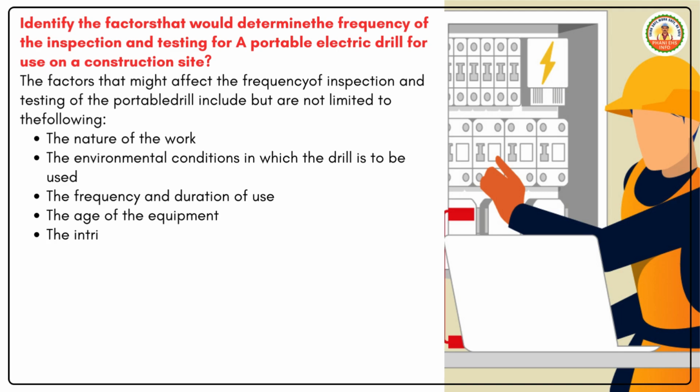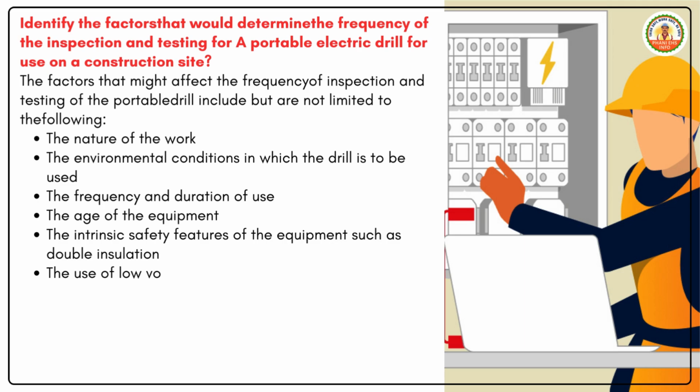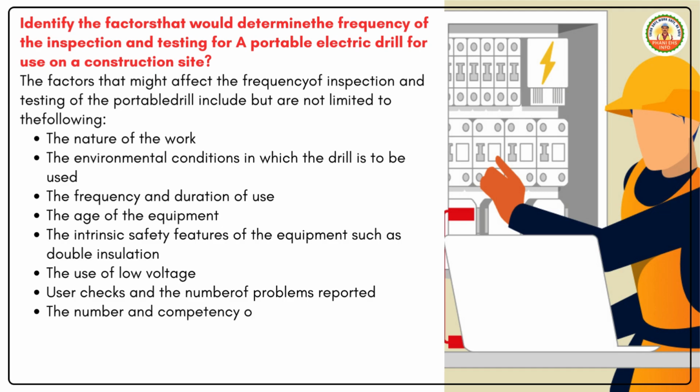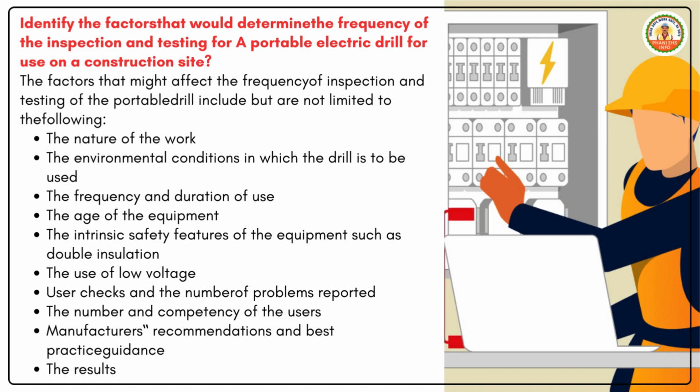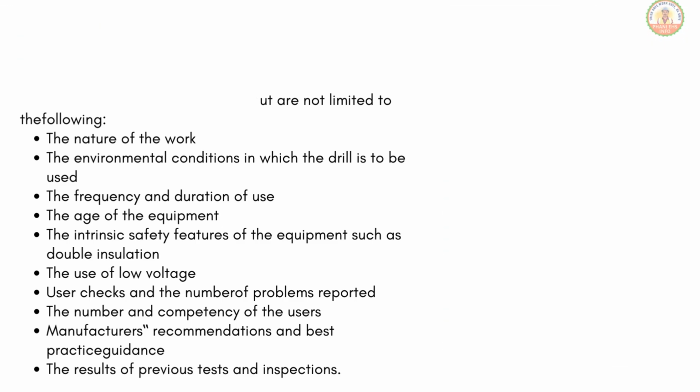The intrinsic safety features of the equipment such as double insulation. The use of low voltage. User checks and the number of problems reported. The number and competency of the users. Manufacturer's recommendations and best practice guidance. The results of previous tests and inspections.